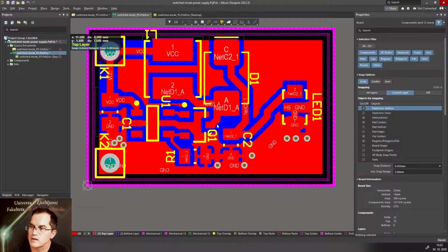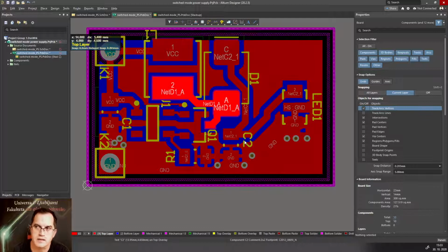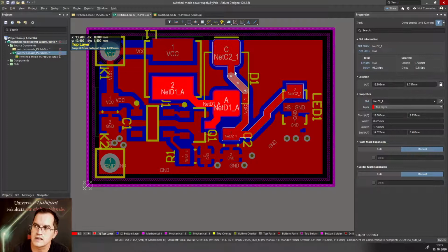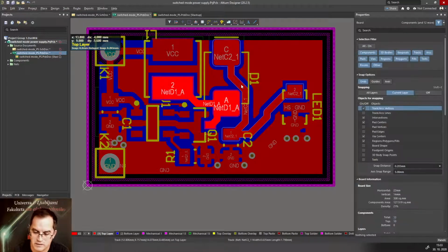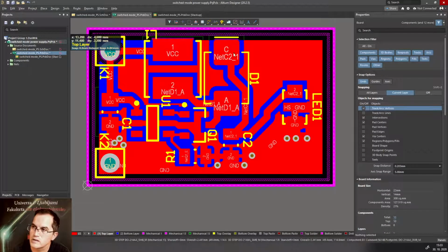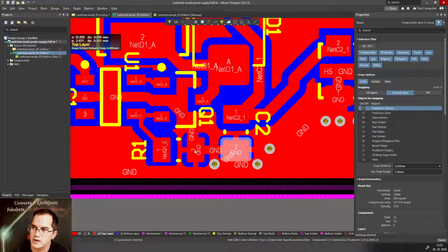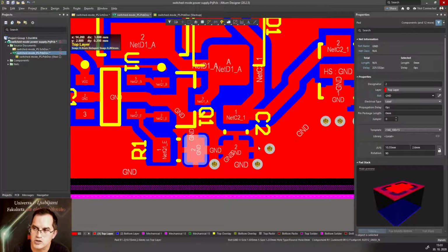So what we ended with: switching node in the middle of the circuit. The high current loop, which contains high frequency currents, is running very, very neatly, being narrow as much as possible. The point where you have the high current loop running on the ground back, where you have the high current spikes, it's between this point and this point, which is very short.